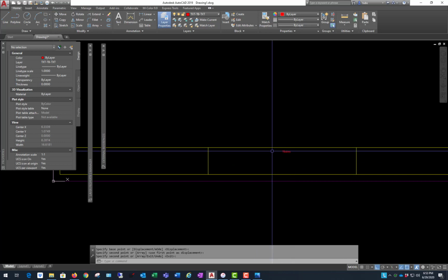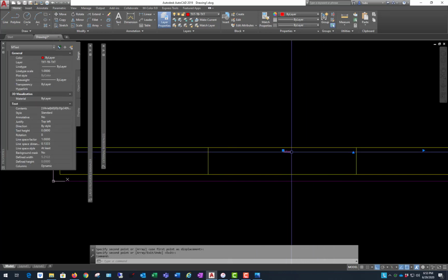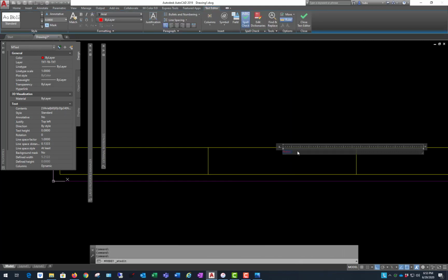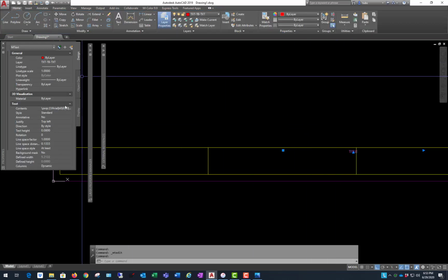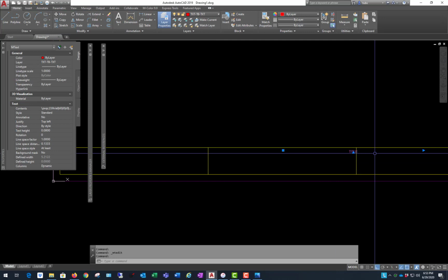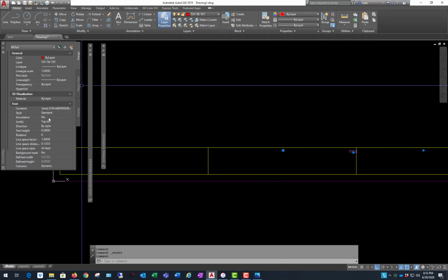And maybe you can see I'm already centering this up because I plan on centering my title in here. I'm going to double click on it, do a Control A, and type in the word title. And this is going to be a placeholder for my title. Do a Control A again. Make sure this is center justified. When I click off it, I can see that the text is center justified within there, but the block of text itself is top left justified.